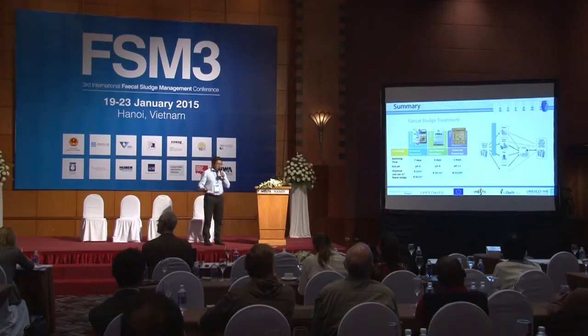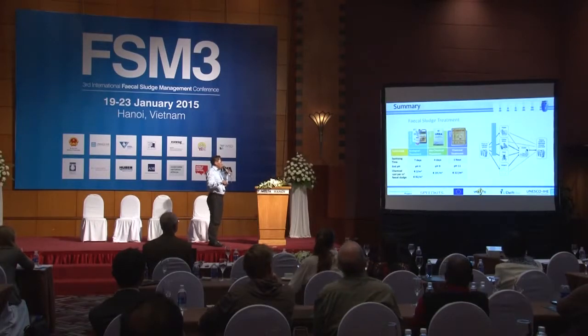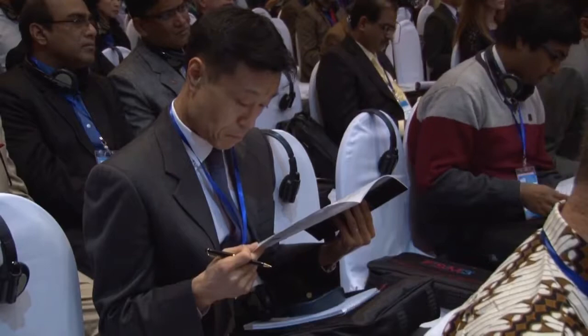Well, summary of these treatment methods. These treatment methods are able to sanitize fecal sludge. Of course, lime is faster. In 1 hour we can have it free of pathogens, but urea takes 4 days and lactic acid takes 7 days. The pH also is very important to mention because we have to look for other solutions for final disposal, because the final products are very acid or very basic.